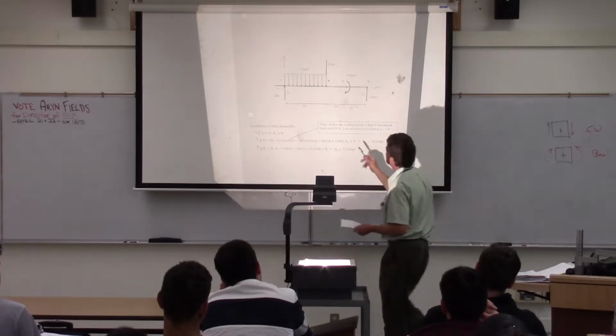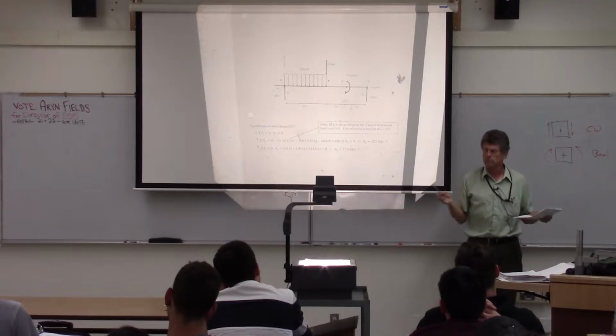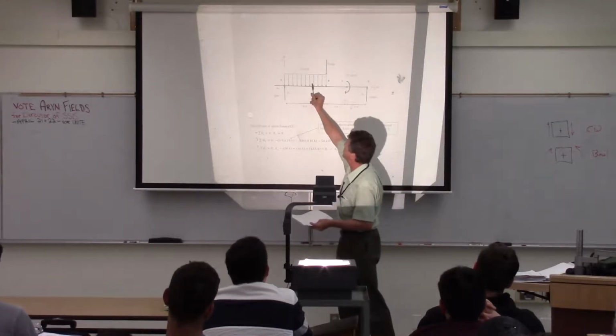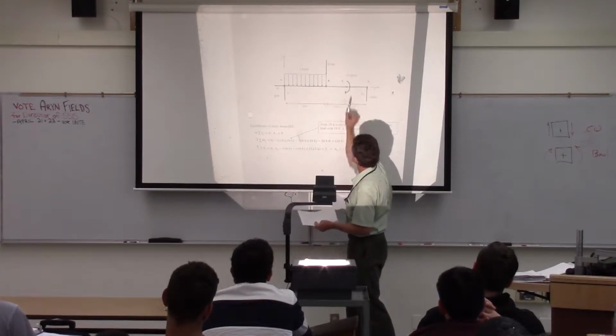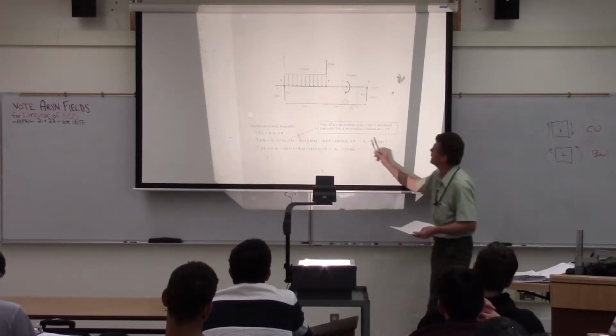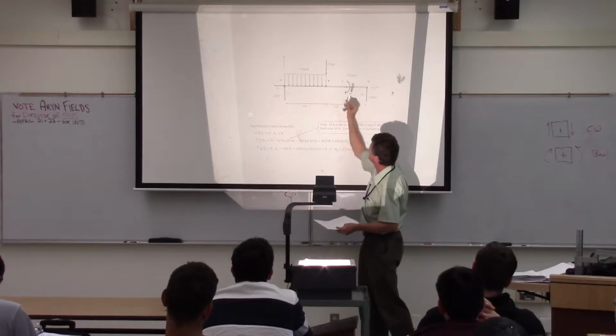Now note, when we get to B, our uniform load disappears. So we're going to have to make another cut. The next place we'll make a cut is between B and C there. Nothing's going on at 11 feet, 12 feet, 13 feet.